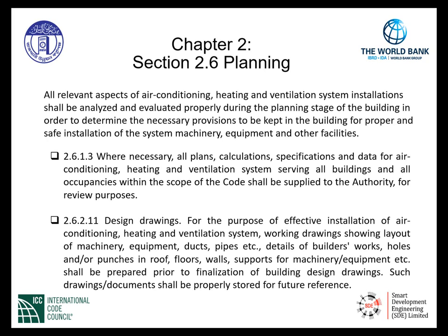Section 2.6.2.11, Design Drawings. For the purpose of effective installation of air conditioning, heating, and ventilation system, working drawings showing layout of machinery, equipment, ducts, pipes, etc., details of builder's works, holes and/or punches in roof, floors, walls, supports for machinery, equipment, etc., shall be prepared prior to finalization of building design drawings.